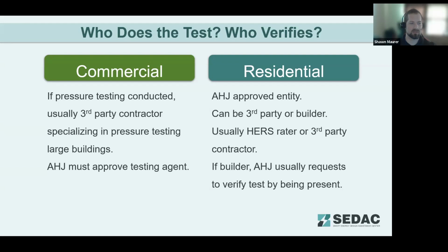The main requirement is that whoever's doing that testing must be approved by the authority having jurisdiction. So your code official has to approve whoever's doing that test. And usually if we see the builder doing the test on the residential side, the code official will usually request to be present at the test to make sure that it's following the proper procedures.